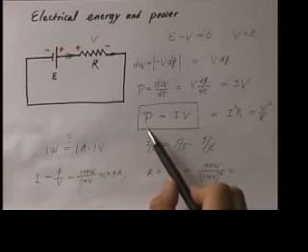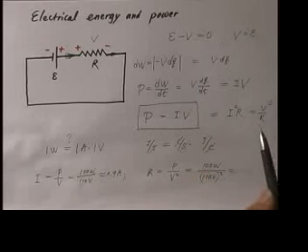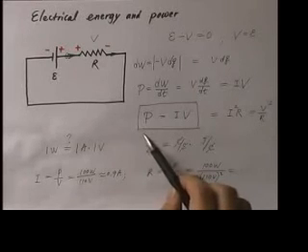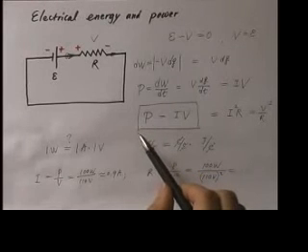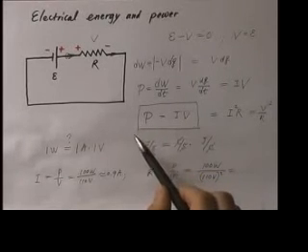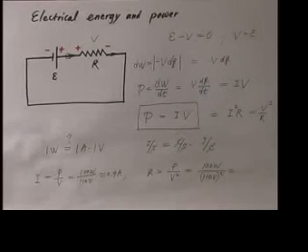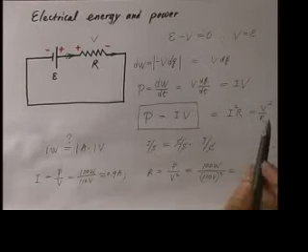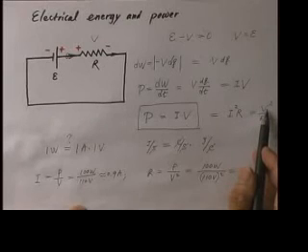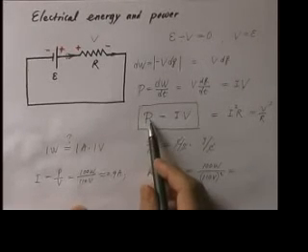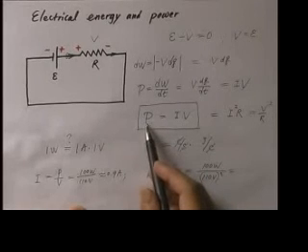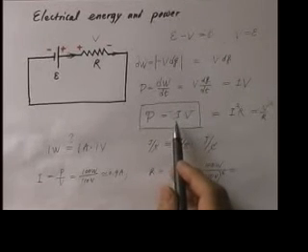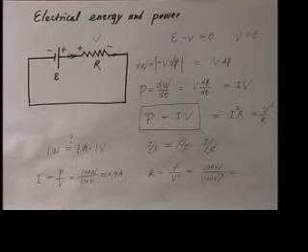On the other hand, if you take the same light bulb and go to Asia, except for Japan, to Asian countries, and you hook it up to a light bulb outlet there, V is 220 volts. Then you can see from this formula that for the same R, P will be 4 times as much because V is doubled. So it's going to glow much brighter, but unfortunately that also means that maybe too much current will flow through it. You might fry it. So that's what happens.